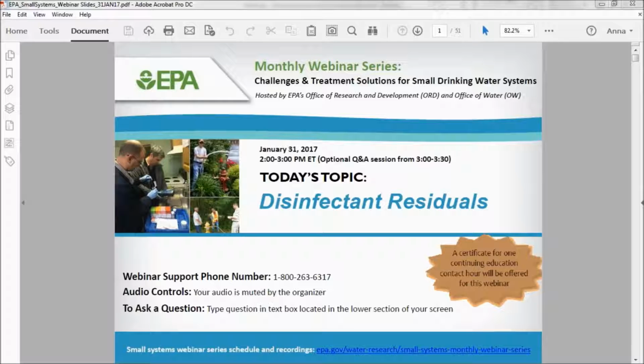Well, as I mentioned earlier, higher pHs tend to suppress or give you a negative interference on your results. What I would suggest, like I said before, is to measure the pH of the final sample. When I say final sample, that's the sample with DPD reagent, and if it's in the 6 to 7 pH range, you should have confidence in that data. If it's higher, that would suggest there's an interference.